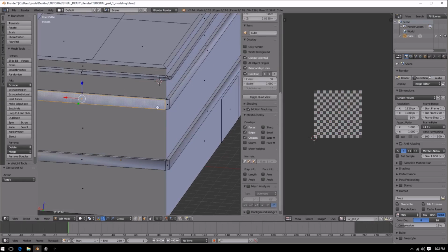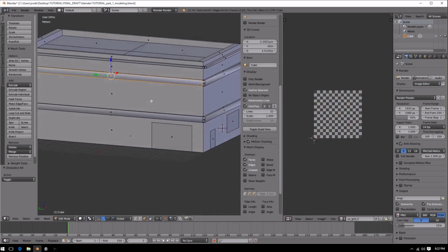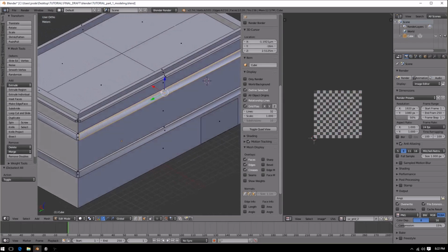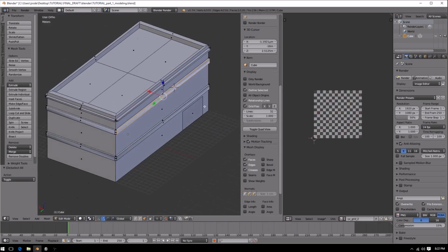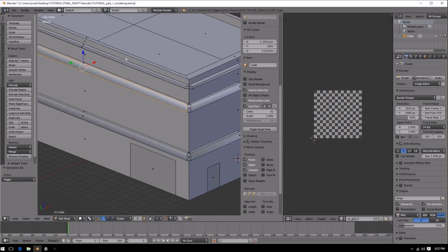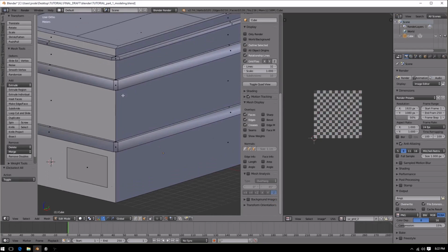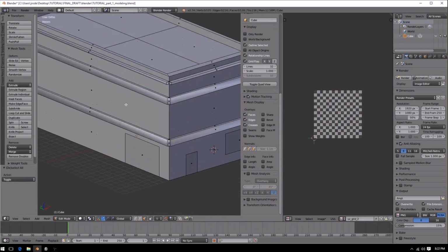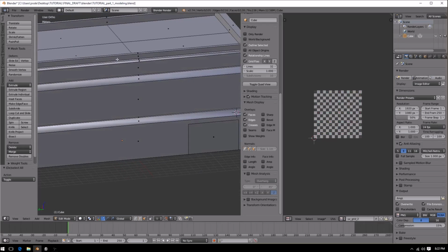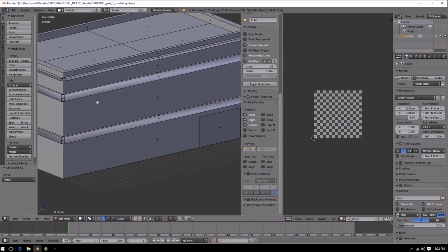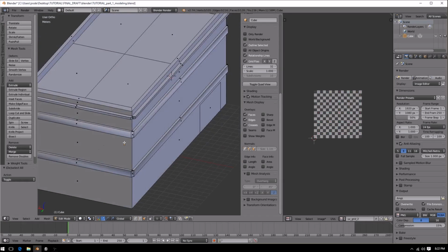I could actually do that with these pieces because they're extremely long, and we're going to have to shrink these UVs, which will end up stretching them, and that's kind of a bad thing. But for this example, I think I'm just going to leave them, and we're going to stretch them onto just a simple gray surface or something, and it won't be too bad. But if you actually have a texture with, I don't know, a cement pattern or something that you actually want to show up, and you shrink these UVs or expand them, you're going to really alter the scaling here. So you'll see what I mean when you get through this.